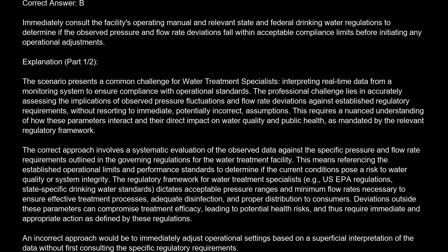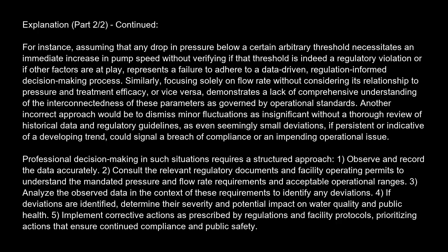An incorrect approach would be to immediately adjust operational settings based on a superficial interpretation of the data, without first consulting the specific regulatory requirements. For instance, assuming that any drop in pressure below a certain arbitrary threshold necessitates an immediate increase in pump speed, without verifying if that threshold is indeed a regulatory violation, or if other factors are at play, represents a failure to adhere to a data-driven, regulation-informed decision-making process. Similarly, focusing solely on flow rate without considering its relationship to pressure and treatment efficacy, or vice versa, demonstrates a lack of comprehensive understanding of the interconnectedness of these parameters as governed by operational standards.